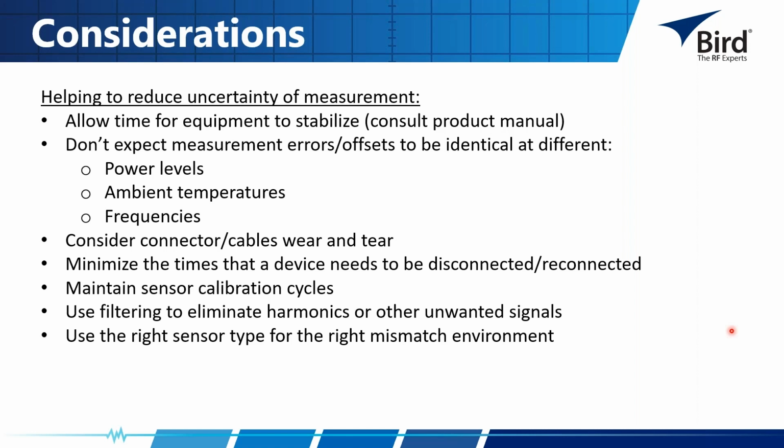A big one that always comes to mind right away for me is allowing time for the equipment to stabilize. There's going to be sensitive electronics in these pieces of measurement equipment, alongside the thermal effects that your desired power level could be having on the equipment in the system.